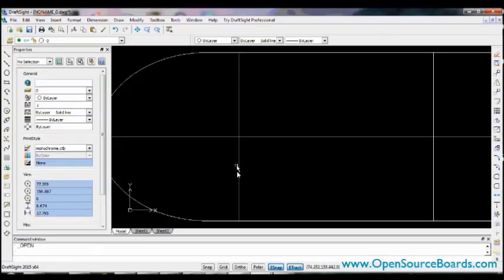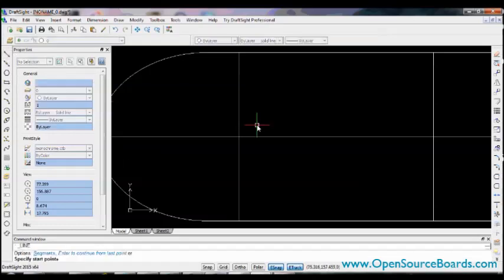This line marks the center line that goes through the outermost holes of our bolt holes. So in order to place this, I'm actually going to make a box with the corners as my center points. So again, I'm just using the line tool for this, and I click at this intersection, and I want to go half the distance of the width. So I want to go up, and remember the width was 1.625, so I need to go half that distance,